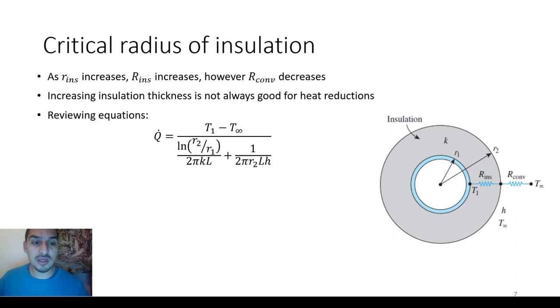And that's why you have to put an insulating material, so that this insulation would prevent the heat from transferring from here to outside, or the other way if it's cold or hot. To do this, you have to pick the insulation thickness, and to take everything into consideration, you have to think of heat transfer from here to here as passing by two types of resistance: the resistance due to the insulation thickness, by conduction, and the resistance by convection from the outer side of the pipeline to the air, or whatever the medium outside.